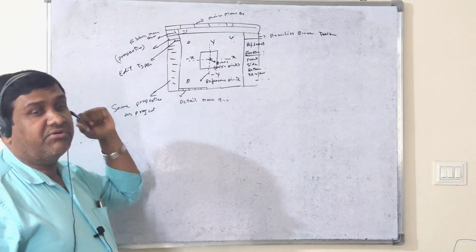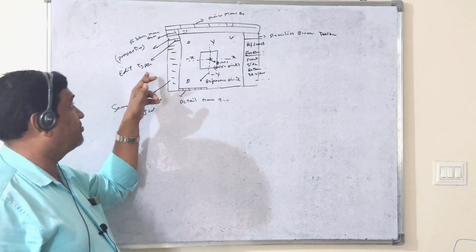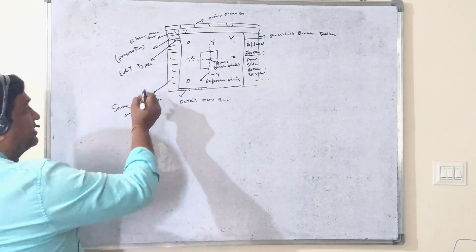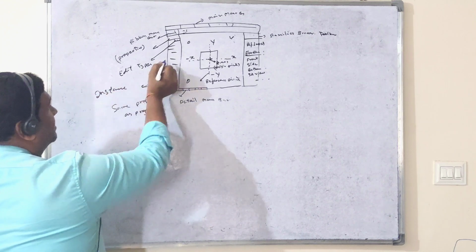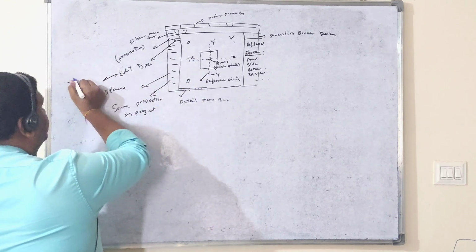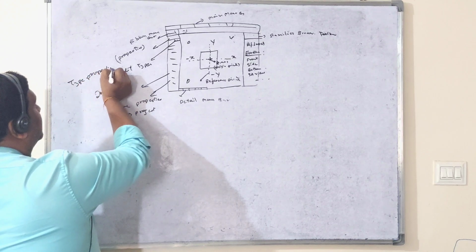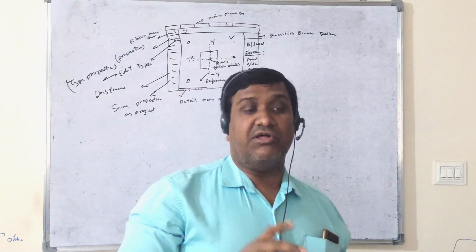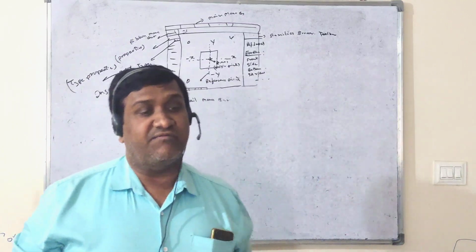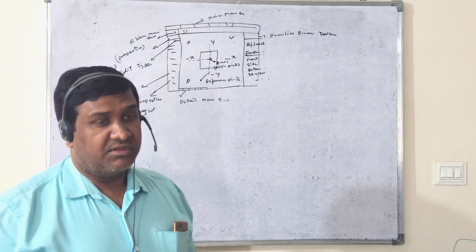That's why in the properties toolbar it shows instance properties and type properties, and this Edit Type is nothing but type properties. Everything is the same, there is no change. Only the concept and view of family creation is different. Got it?